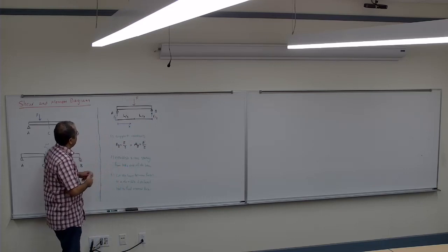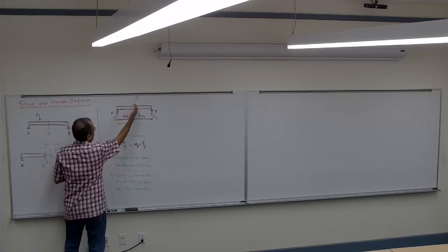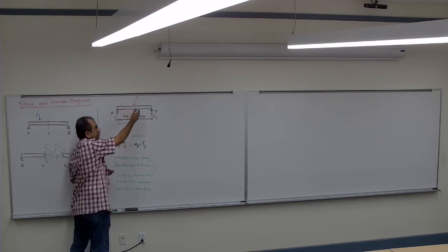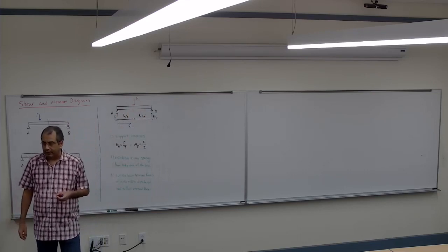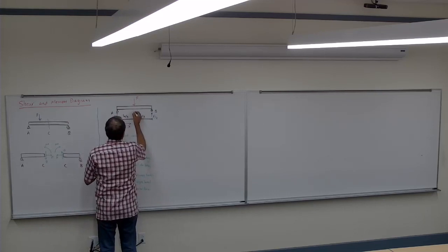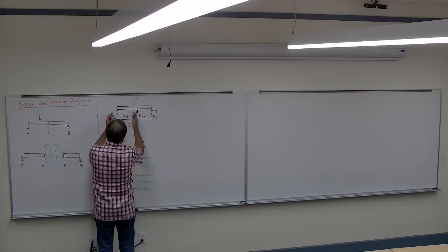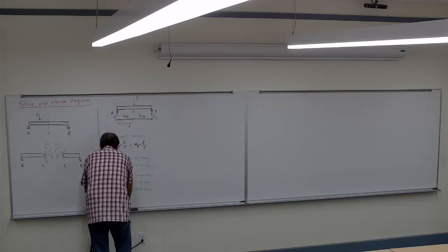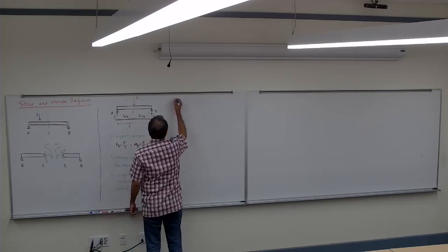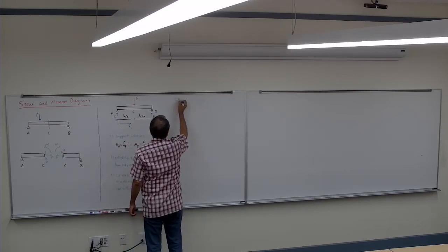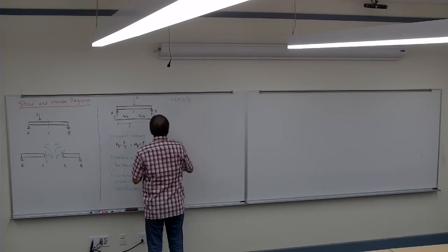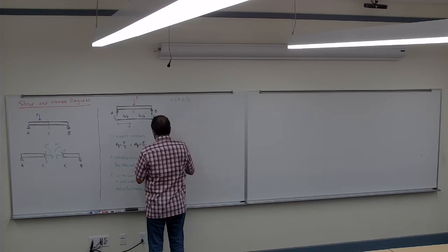So look at here, between the forces. I have one force here, so I have to cut it once between A and the middle of the beam, and once between the middle of the beam and the end of the beam. Let's call this point C, so once between AC and once between CB. For the first section, x is between 0 and half of L. So that's the first step.